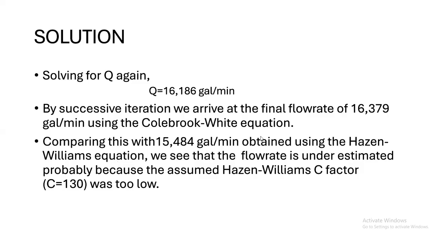So if you are not familiar with your system or your pipe system, I would advise you to use the Colebrook-White equation instead of the Hazen-Williams equation, since it gives a more accurate figure or calculation. But let's say now you're used to your pipe, like firefighters. Now they know the effect of their system, so they can actually use the Hazen-Williams equation because it's easier to use, easy and fast.